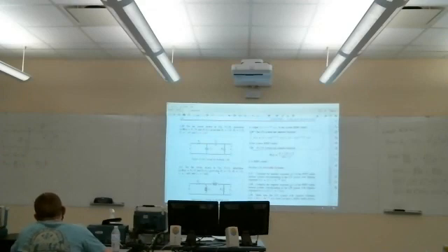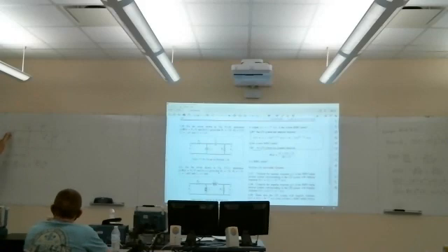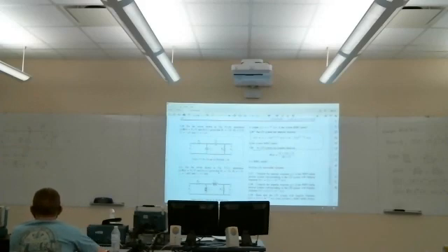I'm almost done. The next steps I want to do are actually, I know the voltage across this cap, so I can get that current. And then now I can get the total current there. It's going to be the sum of those two. And then I can get the input voltage from that loop. So it's a little bit of algebra. I think it turns out to be easier than working it from a forward method, though. It usually does on these ladder type problems.